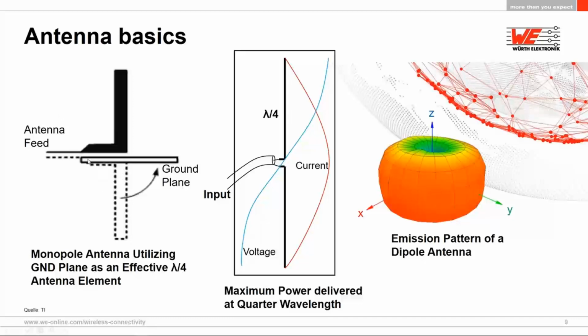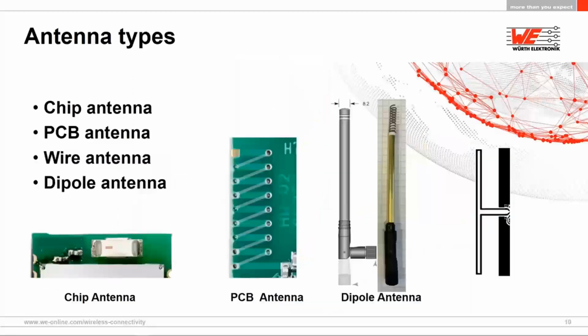Let's have a look at the left here. The negative part of the antenna could, on your PCB, also be part of the ground plane, and you would still have sufficient antenna on the positive side to actually get an electromagnetic signal out. Right, that was a bit of theory in the background. Let's have a look. What is the next one?